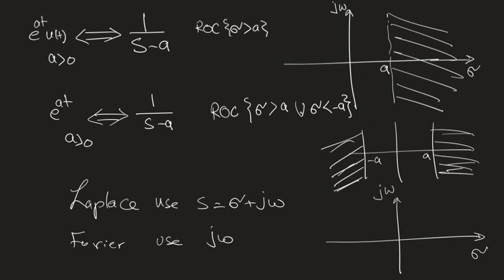It can have a complex frequency with any values in this whole two-dimensional domain, while the Fourier is only a single line in that domain. This is why the Laplace is a much more generalized representation. So simply, the Fourier is only when you substitute S equals j omega, without any possible real value for sigma. Sigma becomes 0. So this is where you have your Fourier.